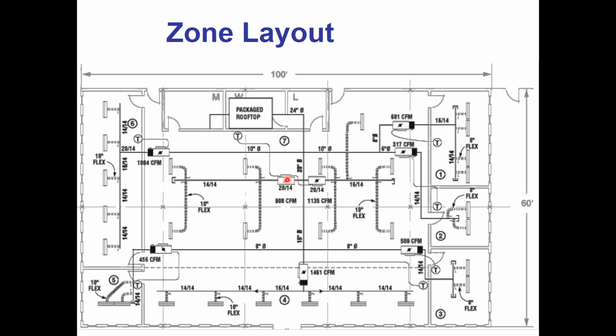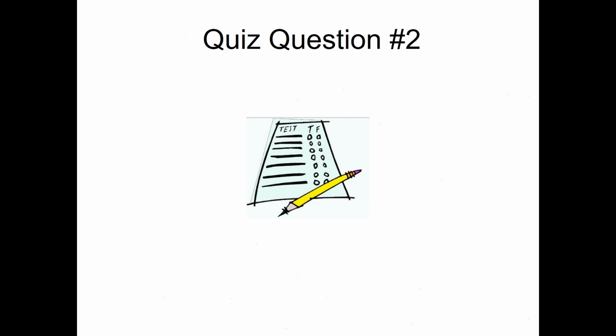An interior zone needs cooling on a minus 20-degree day. So I need to have that cold air available for those guys at all times. So that makes it really hard for me to ping-pong the unit back and forth between heating and cooling. So that's another reason why we end up with cooling-only air handling systems.